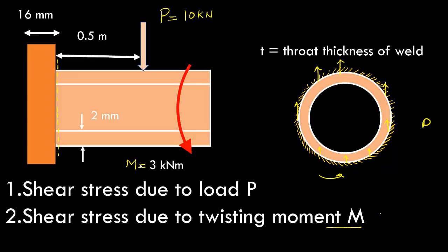So now if I consider rotational equilibrium of this pipe, and if we find what stresses will be generated along the weld, we will see there are tangential forces that will act along this weld in a tangential direction, and these forces are basically trying to prevent the rotation. So there will be a shear stress due to these forces.